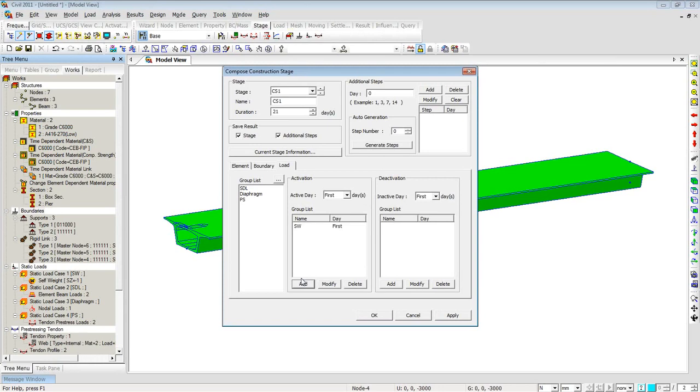So do not try to simulate the self weight of some members in first construction stage through point loads, and then later on activate the span and activate the self weight. This will lead to incorrect results. So you should activate the self weight no matter what happens in the first stage, even though your elements are activated in the following steps.